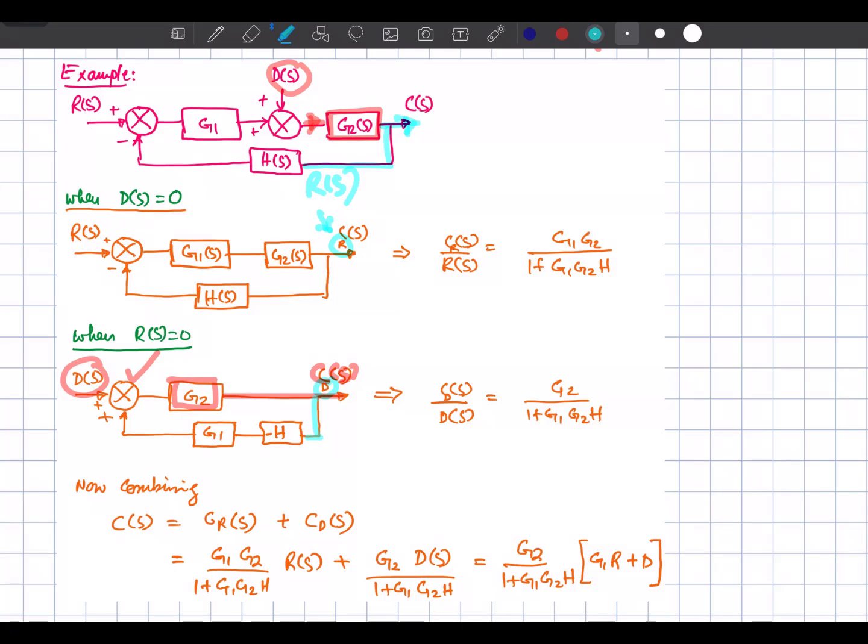Over the feedback path, first of all we will have to traverse this transfer function H(s), and it is coming into the negative one, but this input is considered as 0, so simply it will be considered with the negative sign over here, because 0 minus the signal coming over here will be the negative of that signal. So minus H(s) into this G1, and then finally you are entering into the summing node, and that is with the positive sign. So this makes a closed loop path.